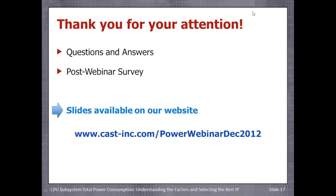Okay, in that case, using a benchmark representative of your application category or the application software of a previous project would be the best way to go. What you really need to be doing is to use some software that would exercise the same modules of the CPU that your final application would also use. So, for example, if your final application heavily uses floating point calculation, you need some benchmark that would exercise that.